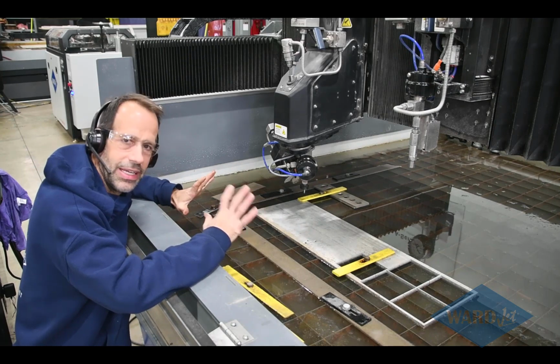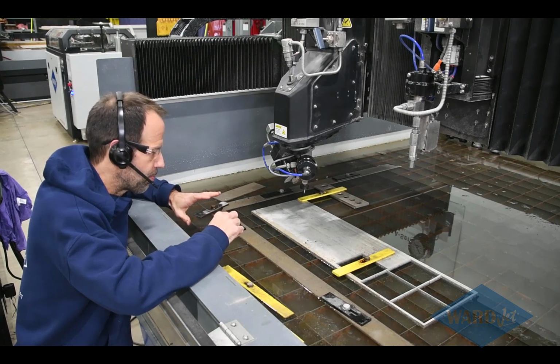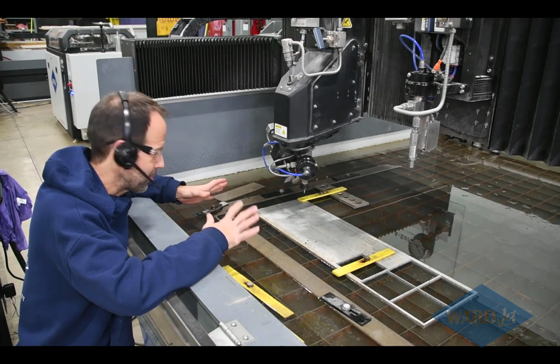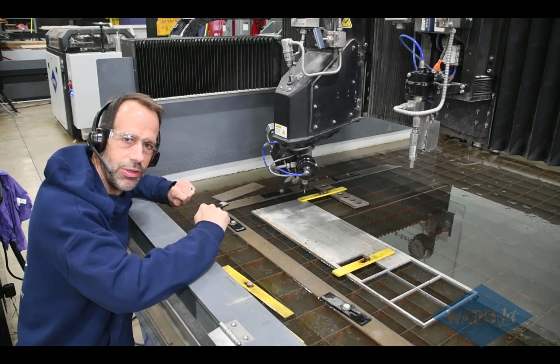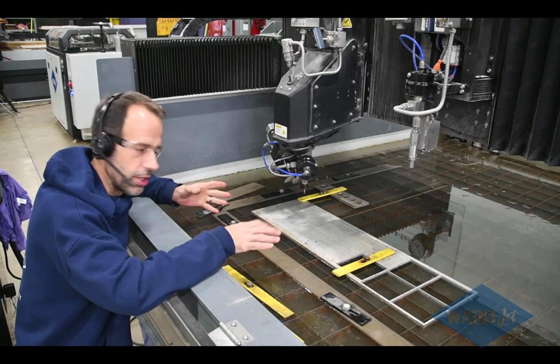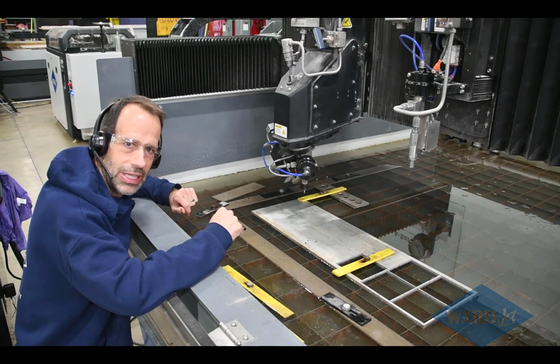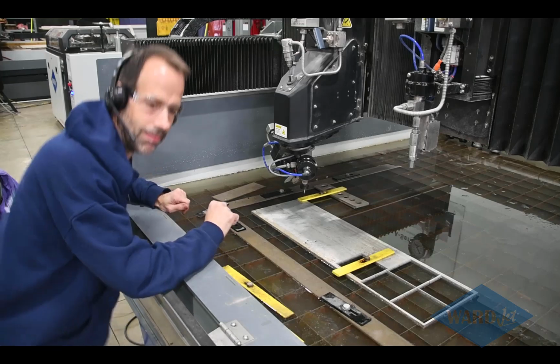And then with that, I'm going to go into IGEMS and actually tell it that we're going to use a work offset position to cut this part. Earlier, I had programmed it with the G92 position. When I got out there, I said, well, I'll just utilize the fixture and we can do a work offset. And work offset's really cool if you're doing a lot of repetitive work in the same location. We've got a whole webinar that talks about that. So let's take a quick look at that and then we'll cut this.